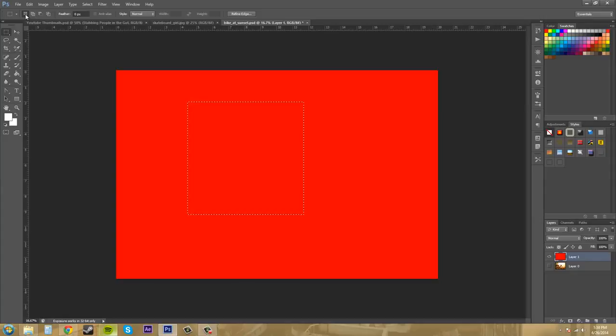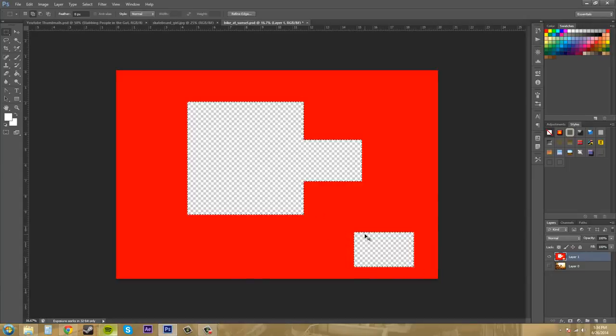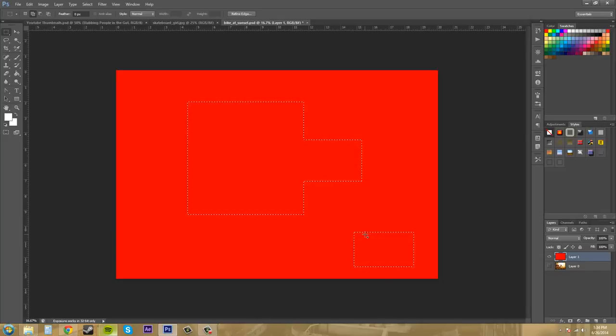So we've got a few options here. We've got the new, which is this first one here, new selection. We've got add to selection. If I click on that and then I add these, it's going to add to the selection that I already have. Or if you're just out here, it's just going to have another separate box for you. And then you can hit delete, and then they all delete. I hit Control Z to go back, and then I can hit Control D to remove my selection so that I have nothing selected. So I'm going to create a new box,